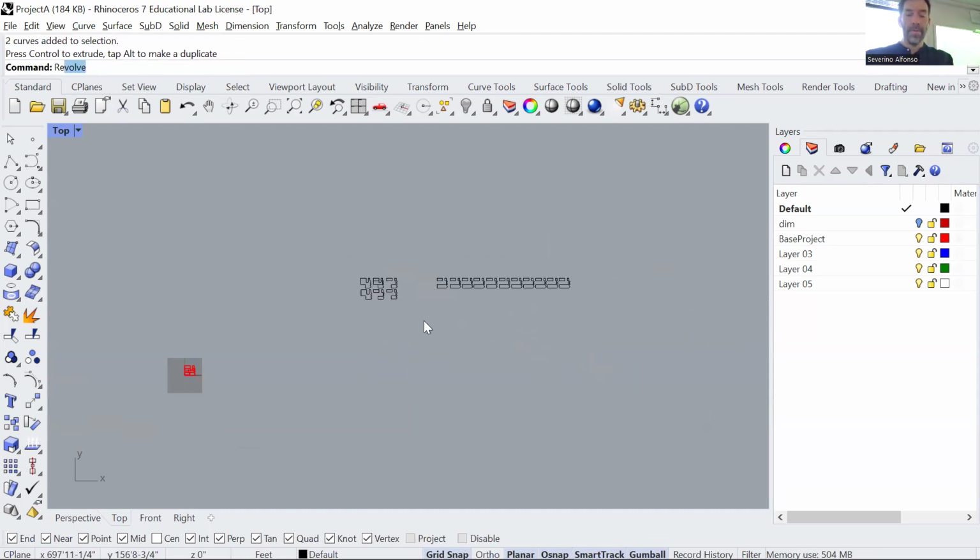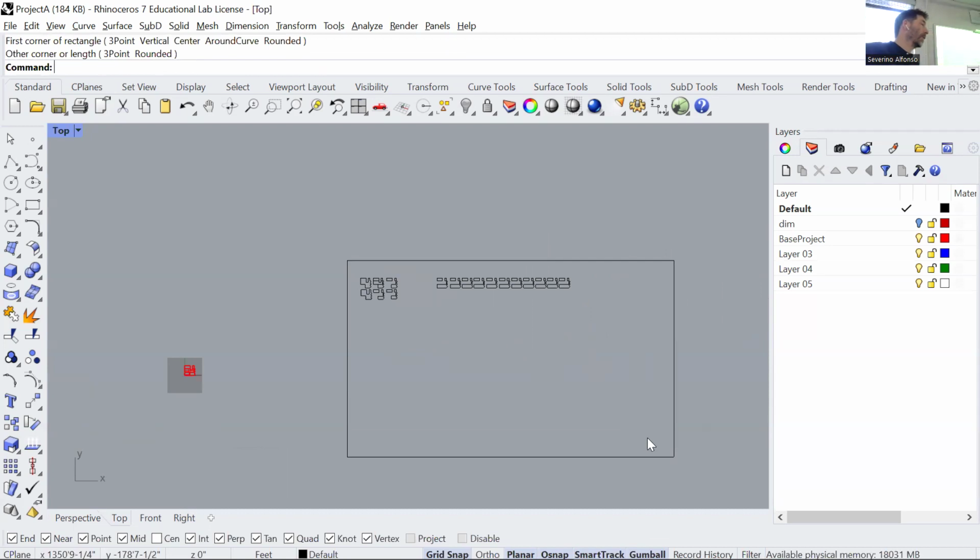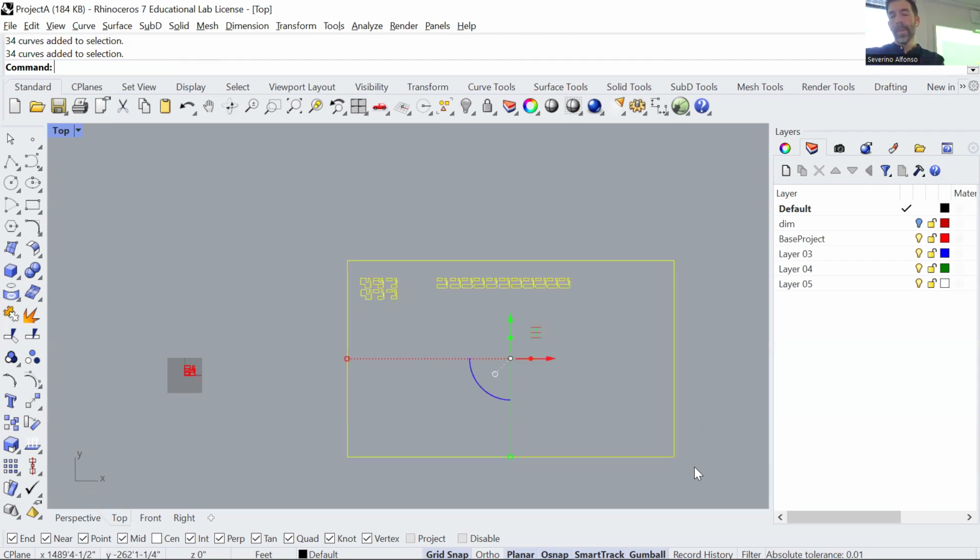And those, and I'm just gonna do it very fast, should be inside a rectangle. And I'm gonna tell you in a second how big it should be. That rectangle is gonna define or symbolize the size of the cutting bed of the laser cutting machine, no? As you can imagine, this laser is like a little machine that goes around cutting stuff, it cannot take a walk outside of the room and invade the earth, no? So it's gonna have to spend its time in a specific XY dimension, okay? So anyway, that's a little bit the process from contour to that rectangle.